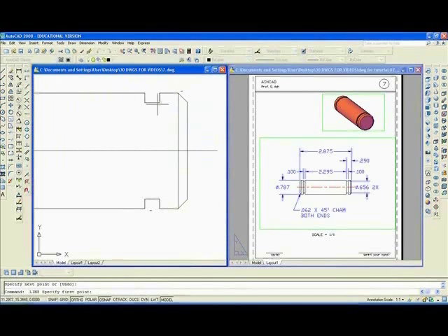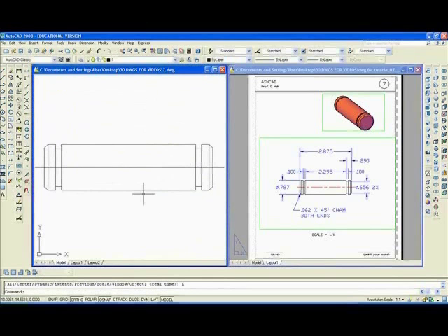Repeat the command, here, here, hit the enter key twice, here, here. Zoom extents, see what it looks like. Hit escape, Z, enter, E, enter. And the drawing looks correct, except that this line in the middle should be a center line.